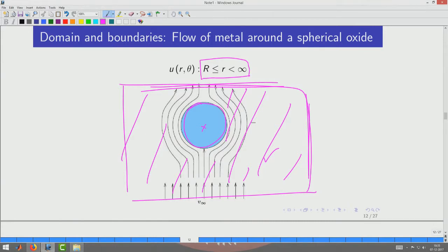Now, we are also choosing the r to be the variable over which the domain is defined, and we can also choose theta to be one of the variables for which the velocity is varying, and we do not have to take both the angles because we can assume that the velocity is symmetric over the vertical axis, so that phi can be dropped off and theta will be there and r will be there. So, like that we can reduce a problem from a 3-dimensional one to an axisymmetric one, and then look at the problem solution. So, like this, in a given situation we make the domain as simple as possible and without losing the essence of the problem.